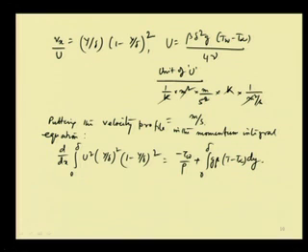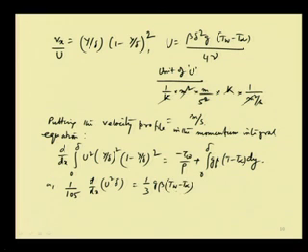Now, T is also a function of y and delta. However, before we put that in, if we work out the left hand side, we get 1 by 105 d dx of u square delta, equal to 1 by 3 g into beta into (T w minus T infinity) into delta, and minus tau w by rho is nothing but nu into u by delta.